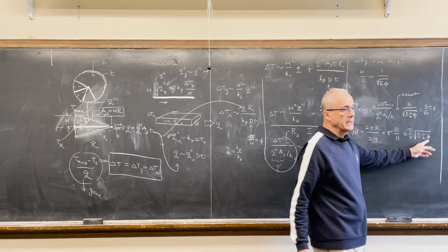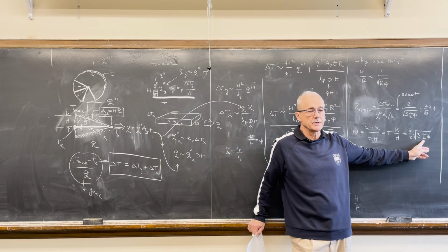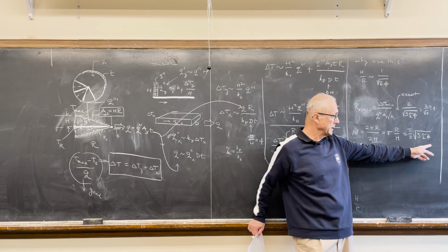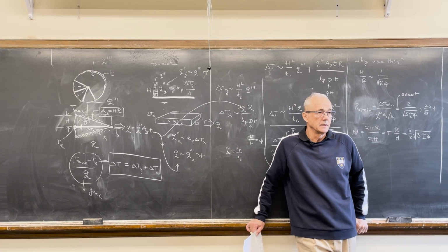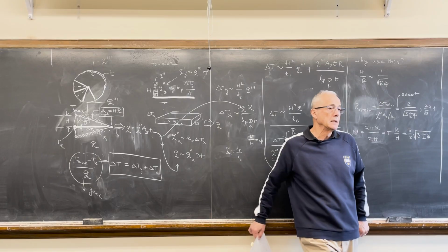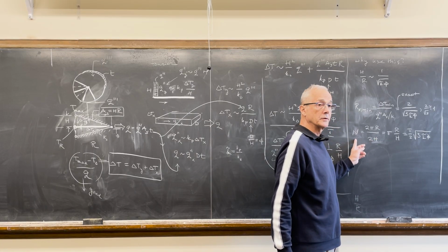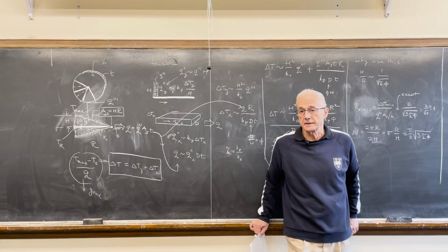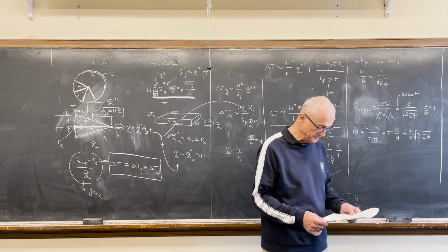So depending on the product of these two dimensionless groups, the ratio of conductivities and then the volumetric fraction of the highly conducting material, you'll have more or fewer of these slices fitting on the disk.